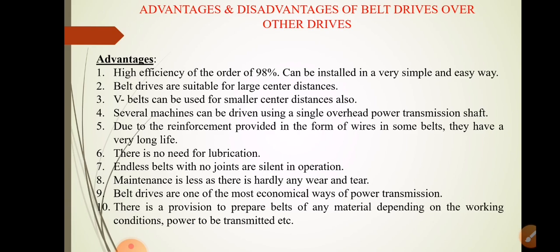Now, what are the advantages and disadvantages of belt drives over other drives? You can have gear drives, chain drives, and so on. So the advantages are, they have sufficiently high efficiency. Then they can be installed in a very simple and easy way. Belt drives obviously are suitable for large center distances, and V belts can also be used for smaller center distances. Sometimes we may encounter a situation where it is not feasible to use gears, nor is it feasible to use a flat belt. Under such circumstances, we can use V belts and transmit motion and power.